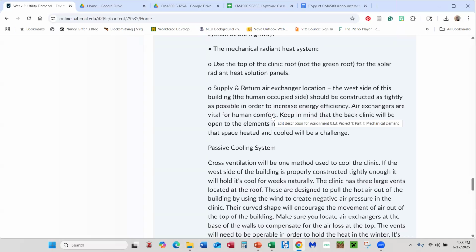And you said the maximum run was what? The hydronic ones I've seen can't hold the heat for more than, I think, 100 feet. So you're going to need multiple lines running. Like a line that runs all the way to the end, splits off right and left and comes back. Then you have another one, so each of them is less than 100 feet.